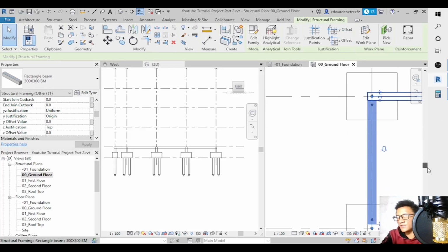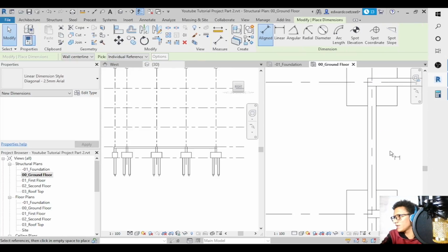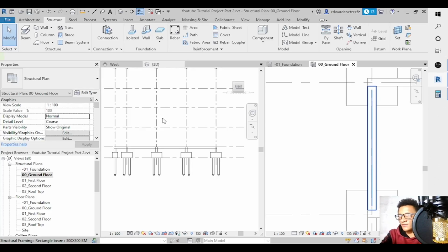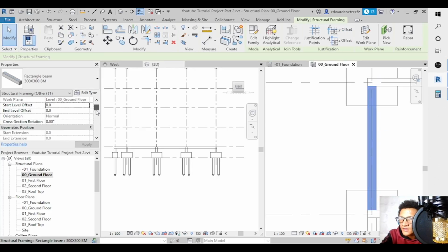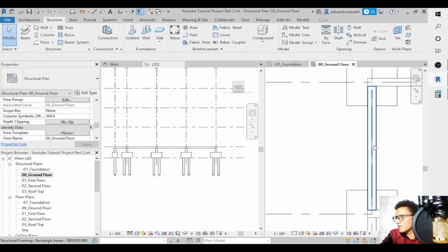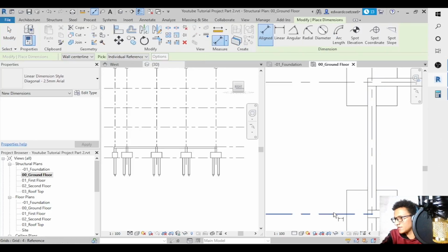So now you can see, let's just check another one. Dimensions, DI. So you know that the beam is supposed to be 4,700. When you select it, you come here, you see that the actual cutting length is 4,700, and basically this is just giving you the center to center. So it's giving you the snap point to snap point. So whenever I say DI, you can see